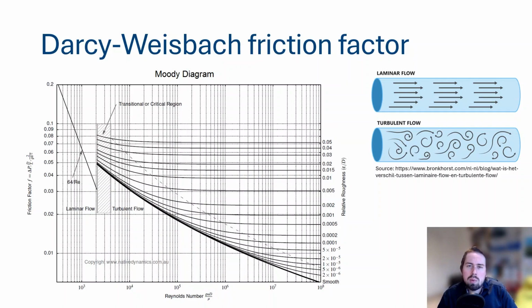Now, of course, when we work with smooth pipes in our typical geothermal systems, these are very, very smooth because it's PE. But if we take, for example, a closer look at steel walls or even concrete pipes, these typically have a very high, it's all relative of course, but a higher relative roughness factor.